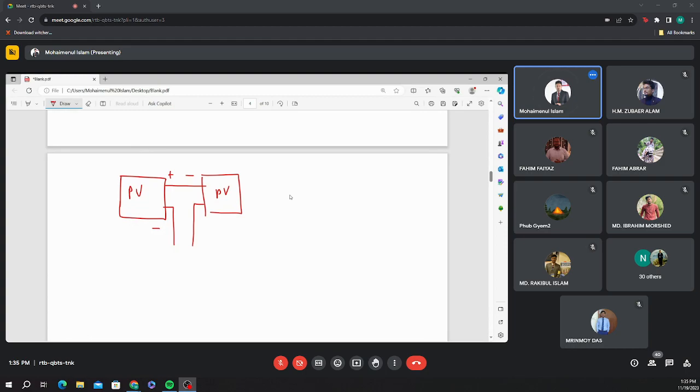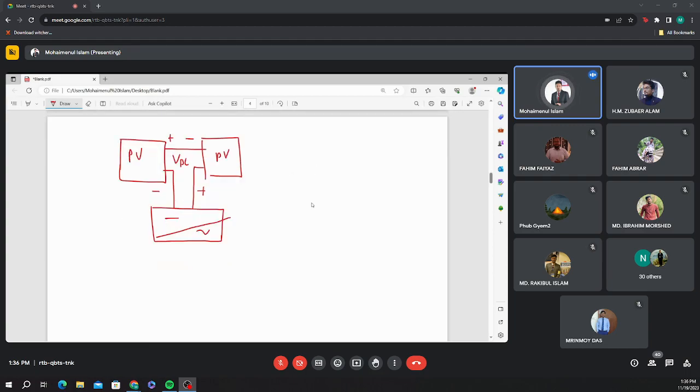So we have the DC again, and after that, you need to connect it with the inverter, right? You need to invert it, so you don't need any charge controller or something like that. They connect it to the inverter. The inverter will provide you the AC output, right? And then you can connect it with the AC load as well.